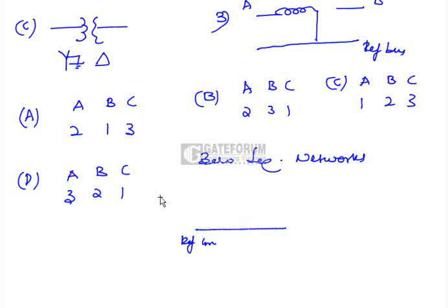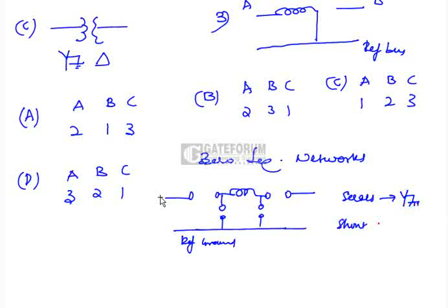Mark the impedance like this, and you have two switches in primary and secondary, and shunt switches in this way. Series switches should close when you have star with grounded. Shunt switches should close when you have a delta connection. Remember this, then the zero sequence networks will be easy.